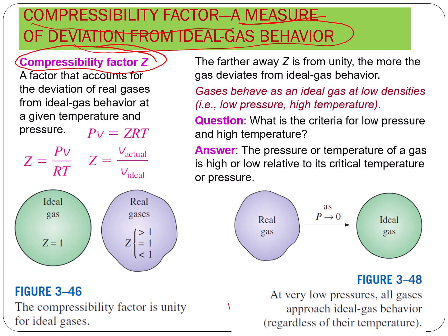So this compressibility factor Z accounts for the deviation of real gas from ideal gas behavior. So how much variation you have as compared to ideal gas. Not all the gases are ideal, so you cannot use the ideal gas equation for any gas. For real gas, we need to make some adjustment, and that can be done using the compressibility factor.